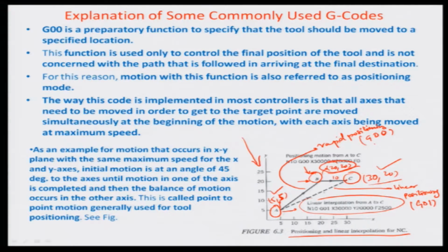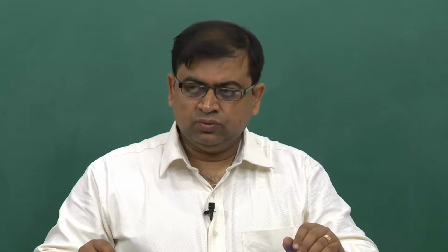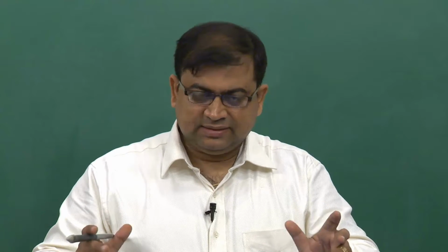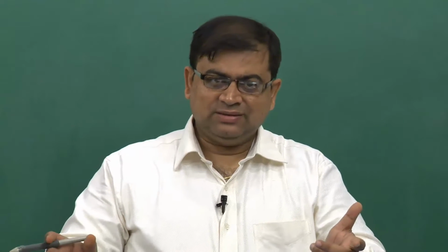So, it is very clear as to what our goal is here when we talk about rapid and linear. Obviously, linear positioning may be used in a case when the actual machining operation has begun and you have to really feed it at a certain rate, because if you are just considerate of the overspeeding factor of the motors alone for the time saving aspect, the material may not behave in a similar manner.